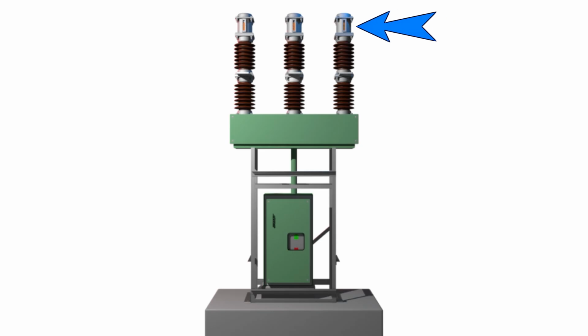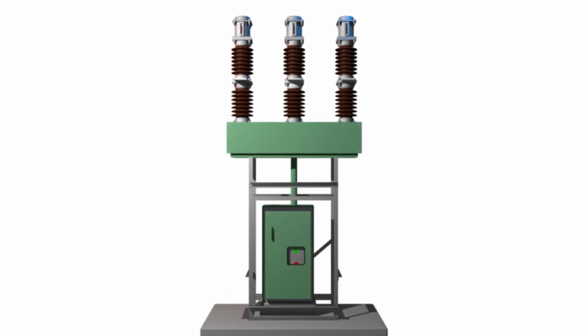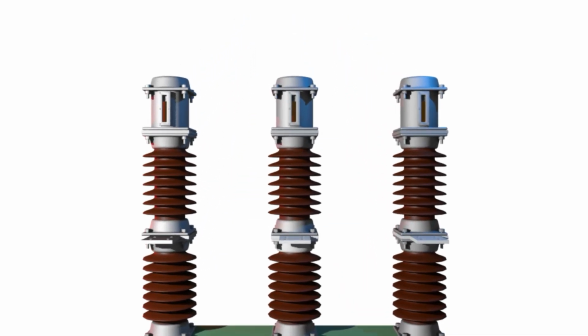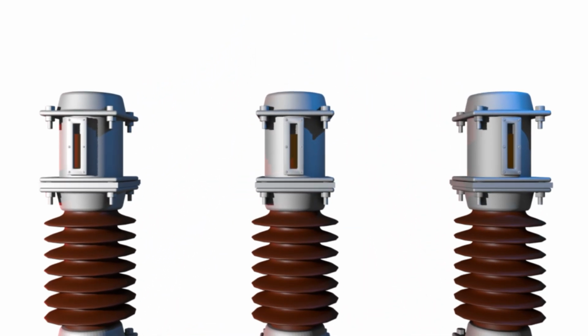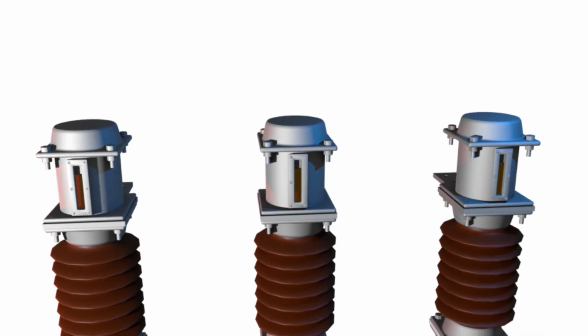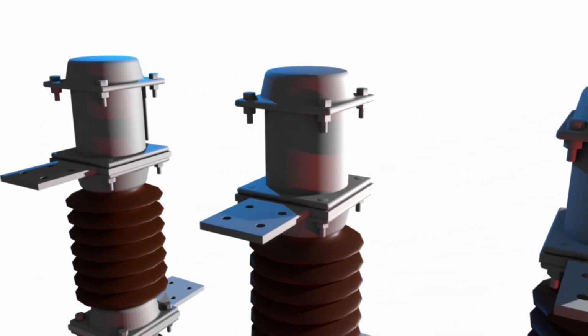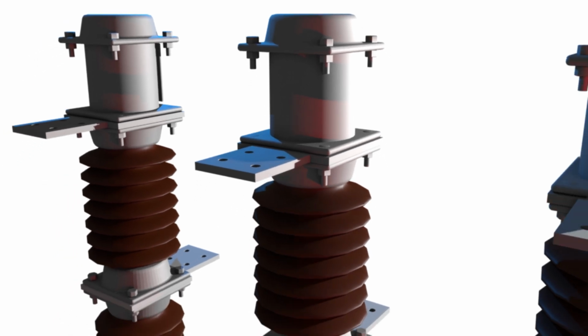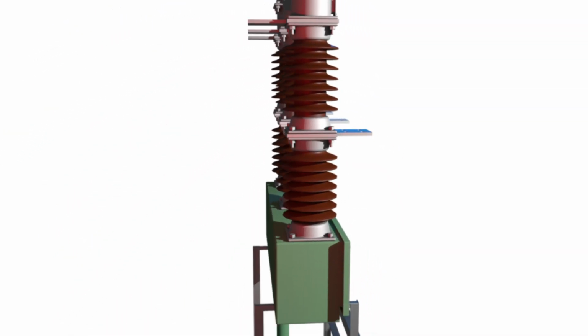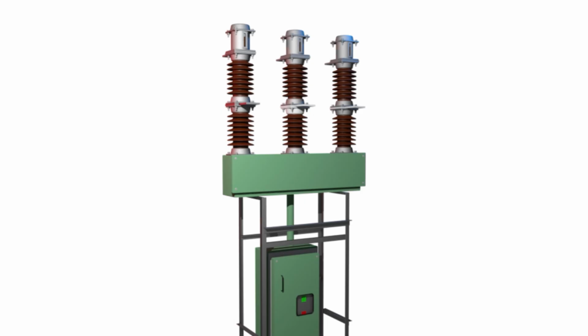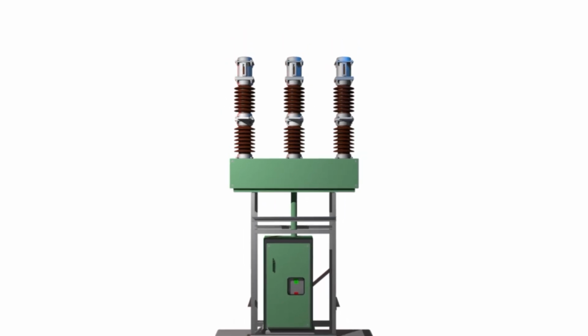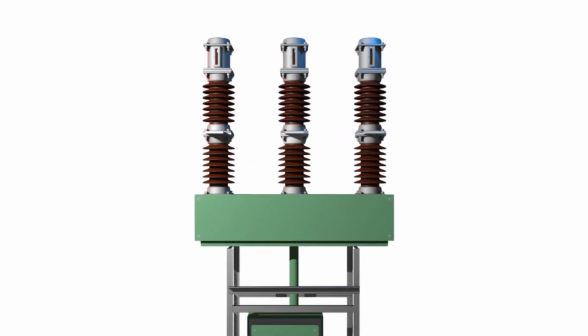There is another compartment attached above the arc quenching chamber, and we refer to it as the top chamber. This top chamber provides the space above the oil level to accommodate the gases formed during the arcing phenomenon. This top chamber also contains an oil level indicator, and just below the top chamber, there is a terminal, which we also refer to as the top terminal of the circuit breaker. That terminal connects to the external circuit and the bottom of the arc chamber. There is another terminal, and that bottom terminal connects the other part of the circuit.